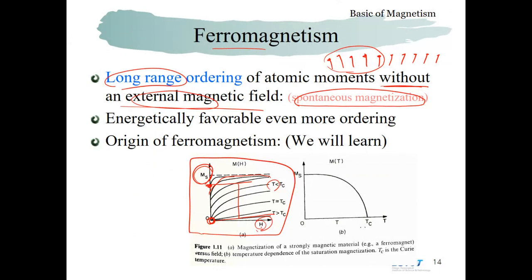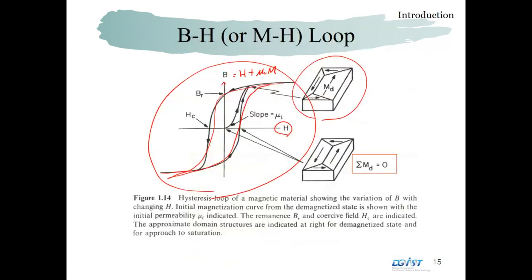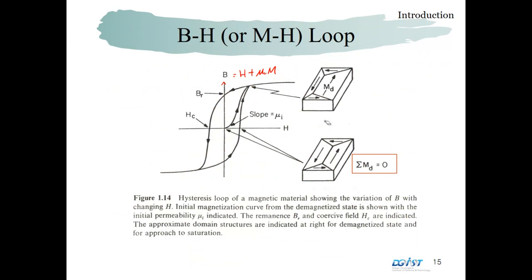We need a very huge field, and this magnetic moment we usually assume constant in most materials. So this plot represents a very global property of the ferromagnetic material, while this plot, how can I say, represents the details of the behavior of the ferromagnetic domains, not the material parameter.